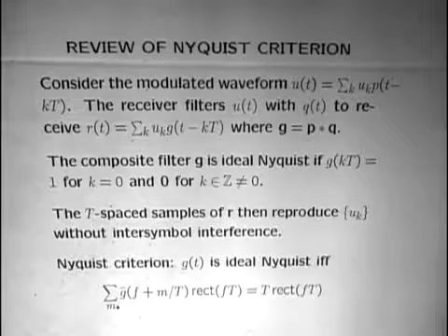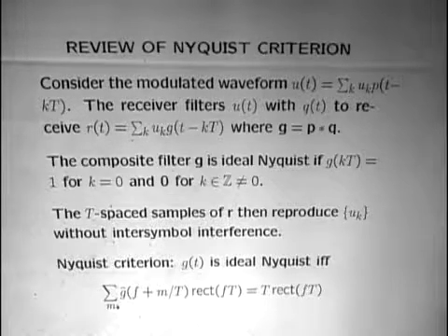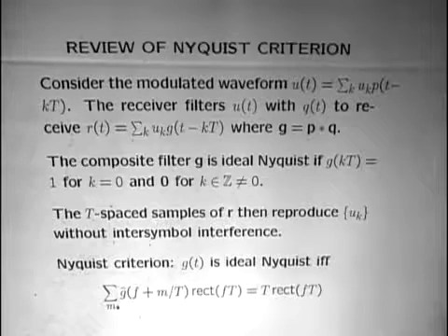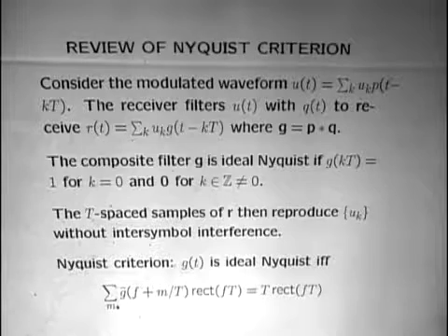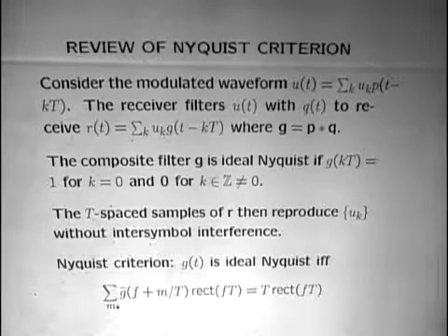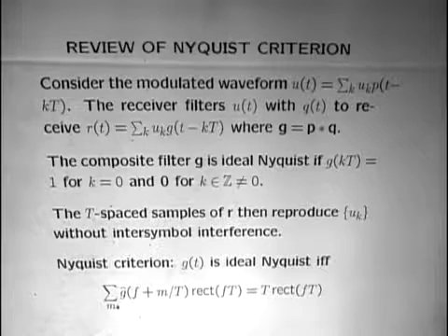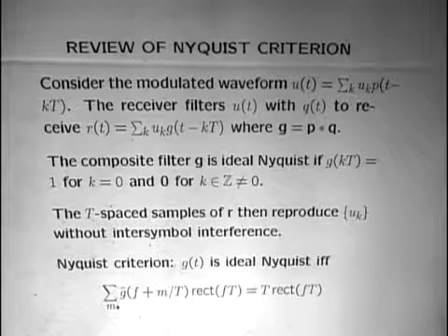But anyway, somehow or other, you implement this, and that is this fundamental step we've been talking about for quite a while now of how do you turn sequences into waveforms? How do you turn waveforms into sequences? It's a fundamental piece of source coding. It's a fundamental piece of channel coding. Here we're doing the channel coding part of it.